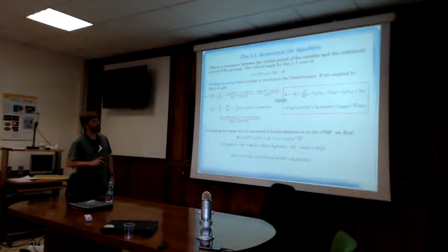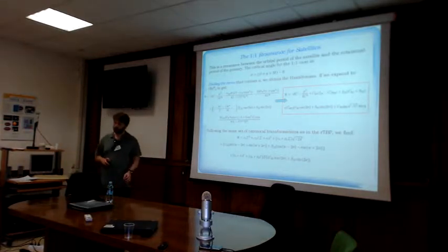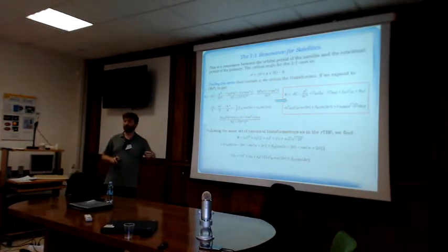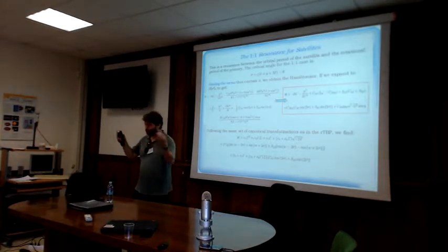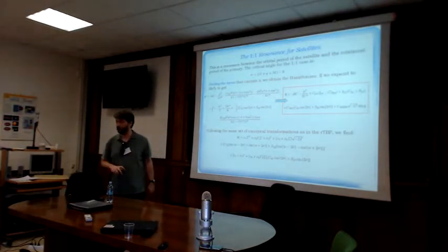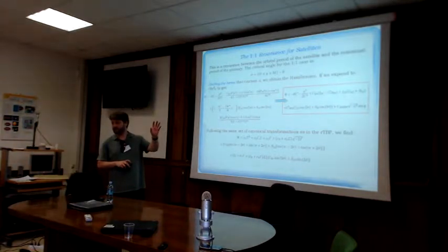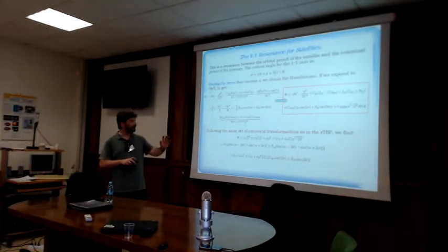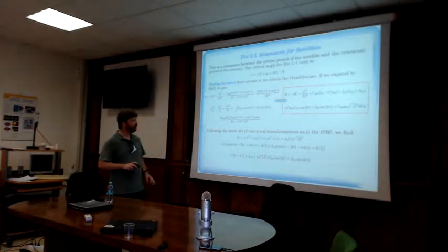Hamiltonian, you would have the Kepler problem plus the correction here. You will have the J2 harmonic, which is not a function of the angles. Okay? And you would also have combinations that have inside 2 sigma, related to the C22 and S22 harmonic coefficients. So if a body doesn't have the sectorial term S22, you can ignore it and keep only the C22 term. And that's the main term that comes as the main term of the Hamiltonian for the resonance.